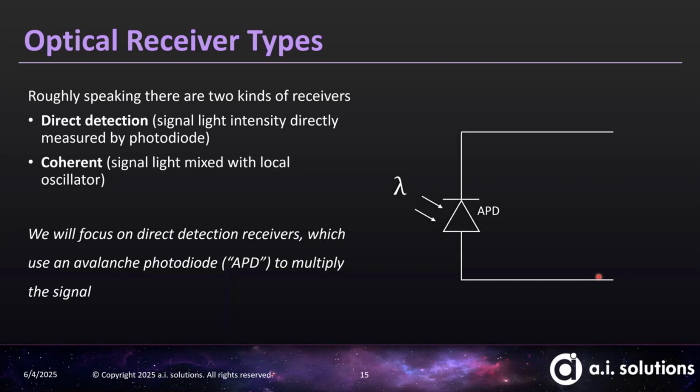Kind of roughly speaking, there's two large families of optical receivers. One is direct detection, where the intensity of the light is what you're detecting. Those first modulation slides I had, the amplitude stuff, are direct detection friendly modulation formats. There are also coherent detectors, homodyne and heterodyne. If you're into radio, you've probably heard this kind of stuff. Basically, you can mix the incoming signal with a local oscillator, and those receivers have different properties, and you can extract some of the wave nature of light doing that.